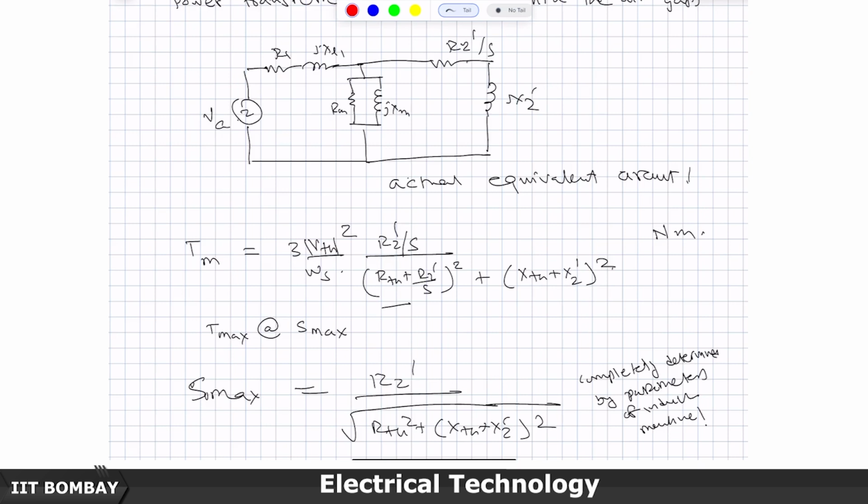So, the voltage quality is disturbed. That is not an acceptable thing. So, direct start of induction motors, small motors is okay, but large motors we usually do not do direct start of the motors.